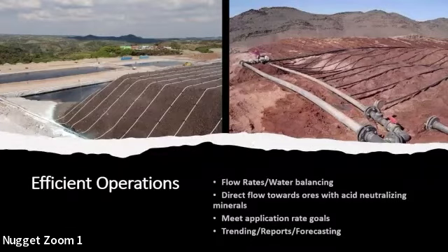This goes into some of the other efficiencies that we can do. Obviously you've got your pump that we have here. We can do vibration monitoring, temperature monitoring, lube monitoring. And then from that, we have the distribution up here. We can also measure the temperature down in the hole. We are developing a beta unit for a downhole probe for measuring the pressure inside.